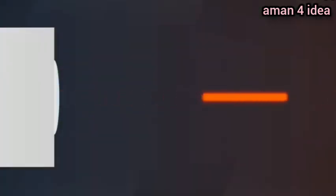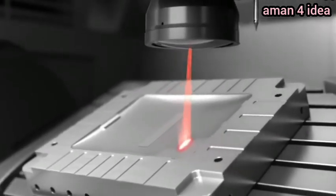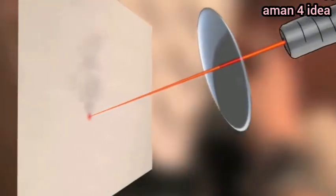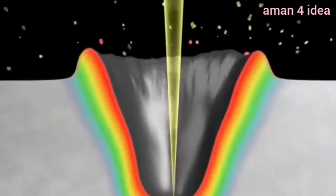Gaining a lot of power, the light is brought to a small spot through a lens, so that when the focused laser is directed at an object, the material in that spot is vaporized due to the heat, which cuts the metal. With a continuous laser, the heat energy spreads over a large area, so the cut part is not clean, but when using a pulse laser, the heat energy cannot spread over a large area, so the cut is very clean.